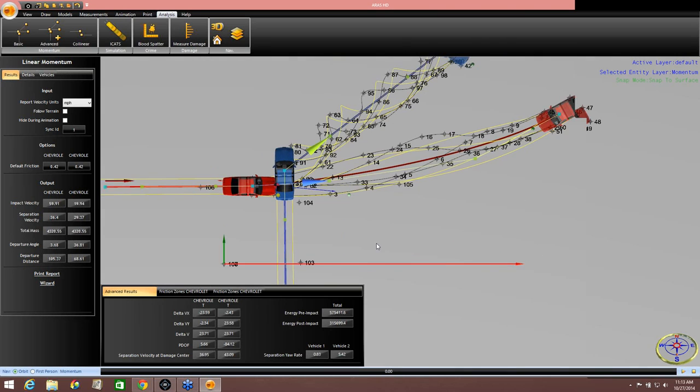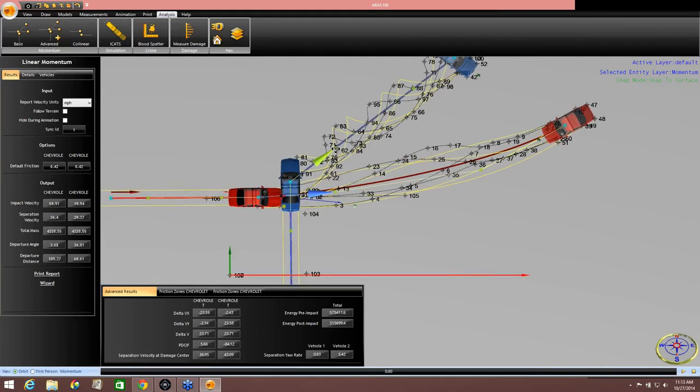And you can see if I change any of this stuff, if I make this departure angle incorrect and go that way, look at my speeds now. Look how they changed. I went from 60 just about to 50 on the one car, and went from 20 up to 28. And as I move this, you can watch those change. They're live. Okay? So if you make a mistake with your departure, you can see how sensitive that can be.